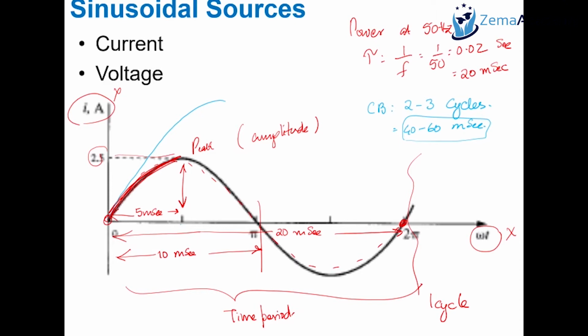But there are physical constraints, or sometimes constraints from the physical properties used to manufacture those devices. It could be a material property or so on. But if you look at the waveform itself, the information is available for the device to act in the first 5 milliseconds or first few milliseconds. And often, those first few milliseconds are the ones that can destroy your equipment as well if the voltage is too high or if the current is too high. So the quicker your protective device can act, the safer the whole system will be.